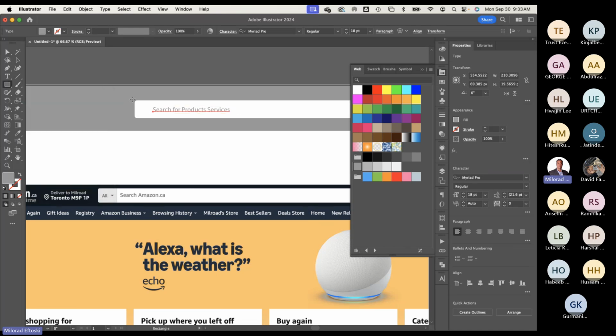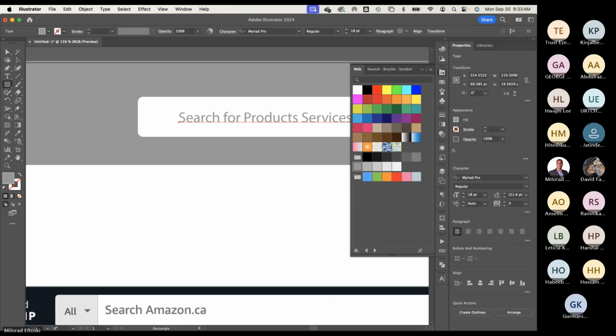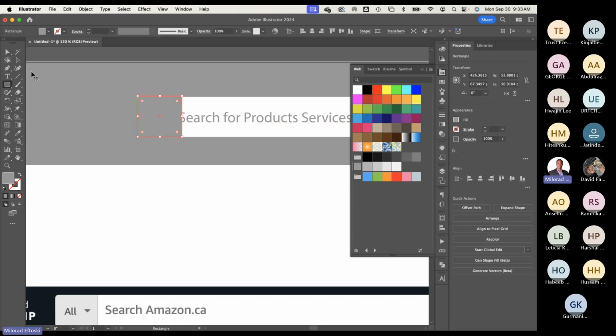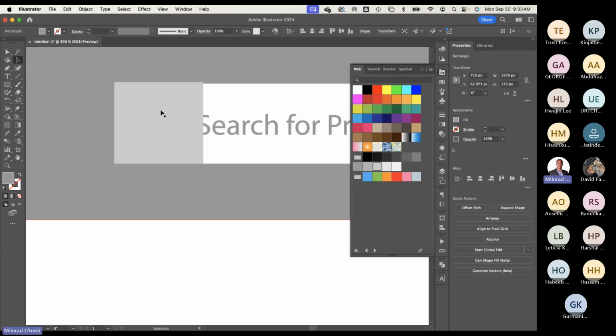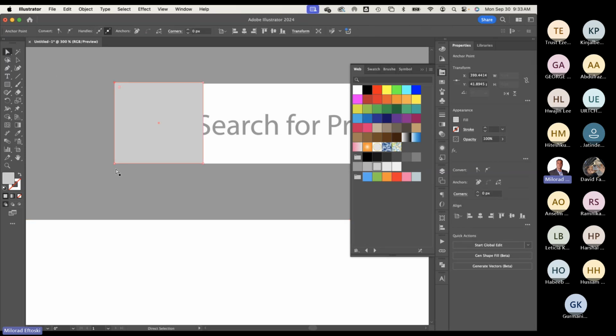So you can definitely add another rectangular shape here. Just going to trace this one like that, move it over. For this one, I'm going to round just the left side of the actual bounding box. I'm going to select this point and that point and just round them to match my existing one here.